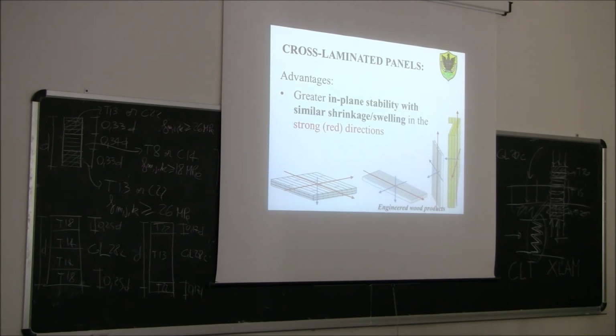Because what we said yesterday is that it's very hard to make a piece of wood shrink in the direction parallel to the grain. So let's consider first this direction here. In this direction here, there are 3 layers oriented parallel to the grain. So those 3 layers here, under moisture content change, will basically keep the same length.